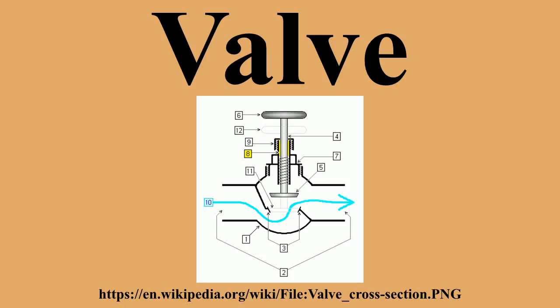Alloy 20 valves are typically used in sulfuric acid plants, whilst monel valves are used in hydrofluoric acid plants. Hastelloy valves are often used in high-temperature applications, such as nuclear plants, whilst Inconel valves are often used in hydrogen applications.